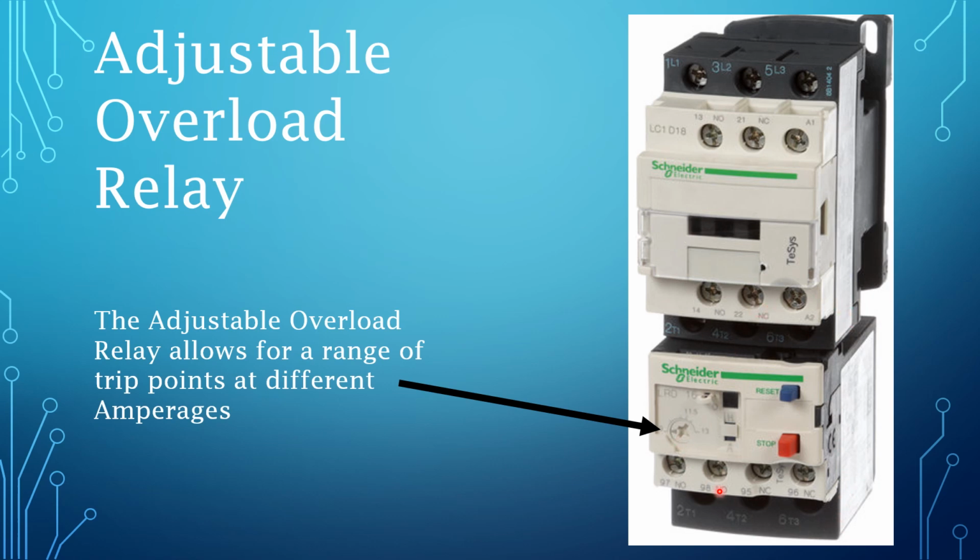And it flows through the adjustable overload heaters. And if you see right here, there's a little set screw. We can adjust the amperage on these, and you can buy these in different sizes so that for the specific motor and specific situation that you're using, you're going to dial in that amperage so that the motor doesn't trip on startup and that it runs smoothly during operation.